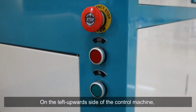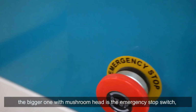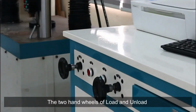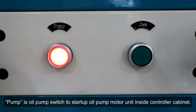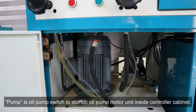On the left upward side of the control machine, there are two power switches. The bigger one with mushroom head is the emergency stop switch, and the other one is the power switch. The two hand wheels of load and unload are used to control loading and unloading hydraulic oil. Pump is oil pump switch to start the pump motor unit inside the controller cabinet.